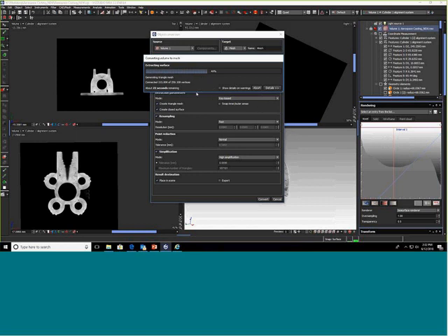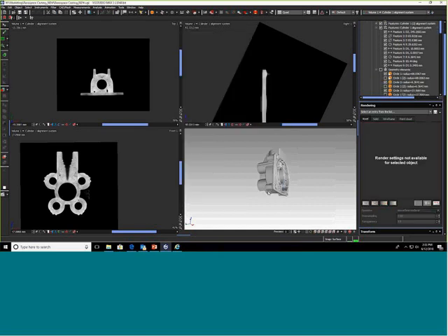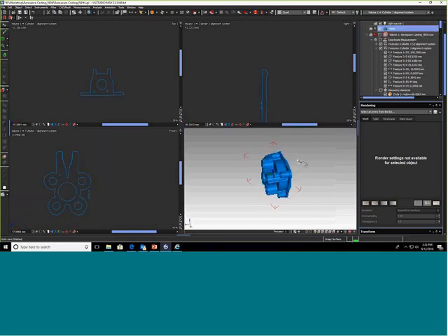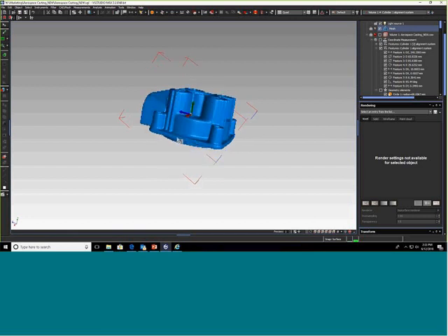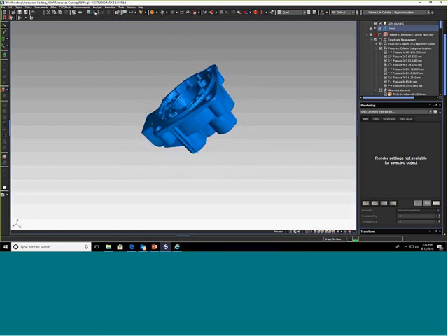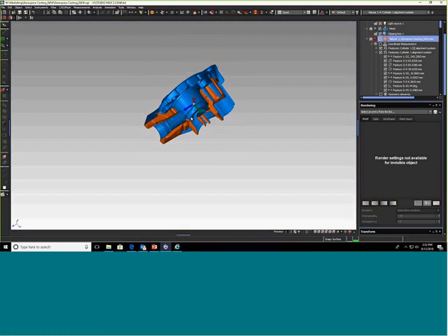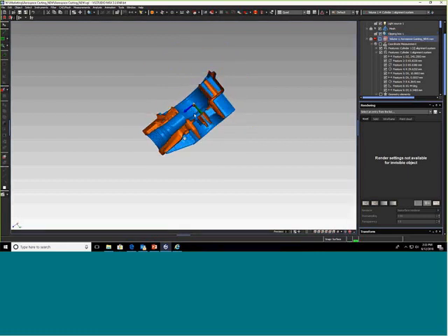Then you can take that into your CAD program of choice, SolidWorks or NX or ProE, and analyze it there if you have already pre-set up finite element analysis or your FEA. What ends up happening is we're able to create, using CT, an exact duplicate that contains all features, not just external.